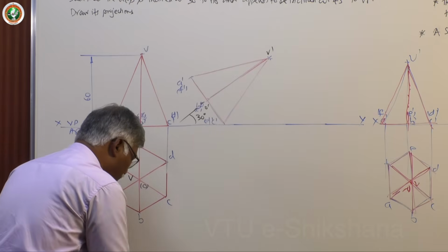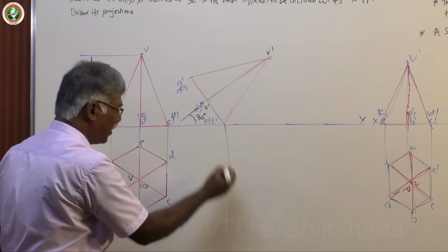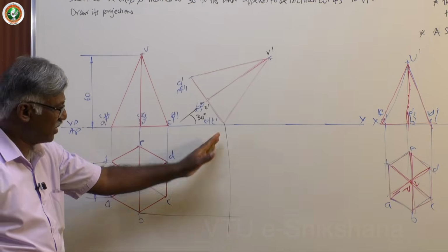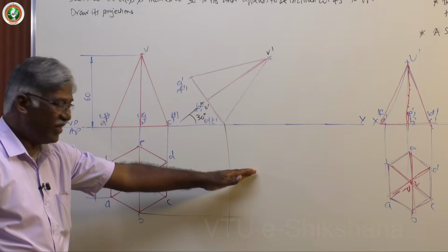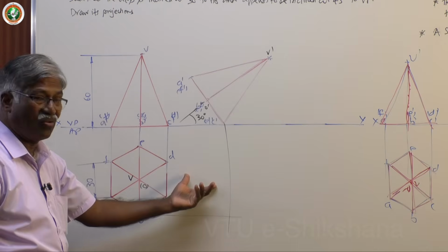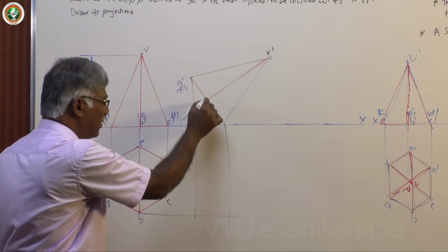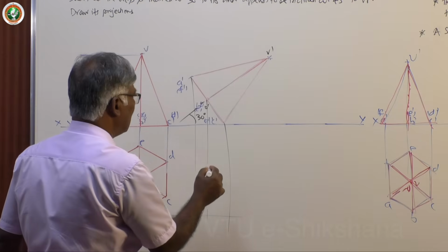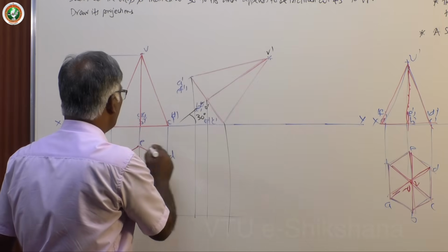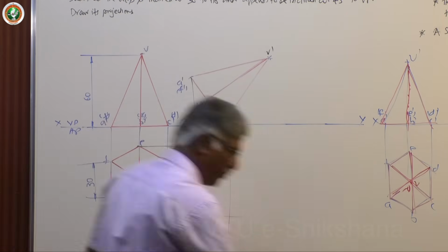Now this front view, second figure front view is completed. How to get the top view of the same? Now, as I told you earlier, better you draw two lines, that is extreme right projection, and bottommost projection for the base only. Now project up to this, which acts as a stopper, again this. Now this is again the top view of the base.